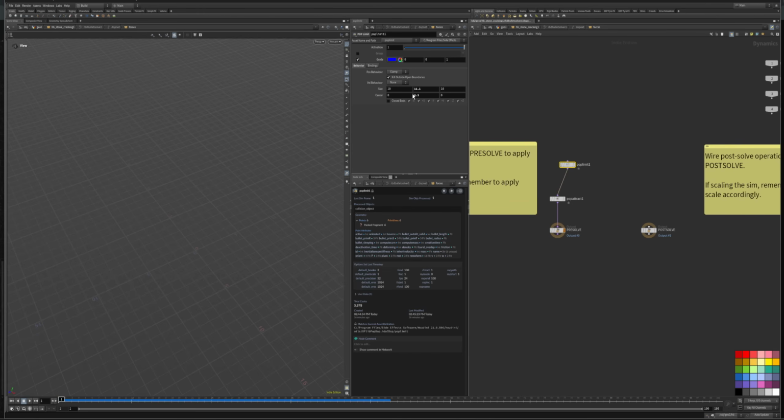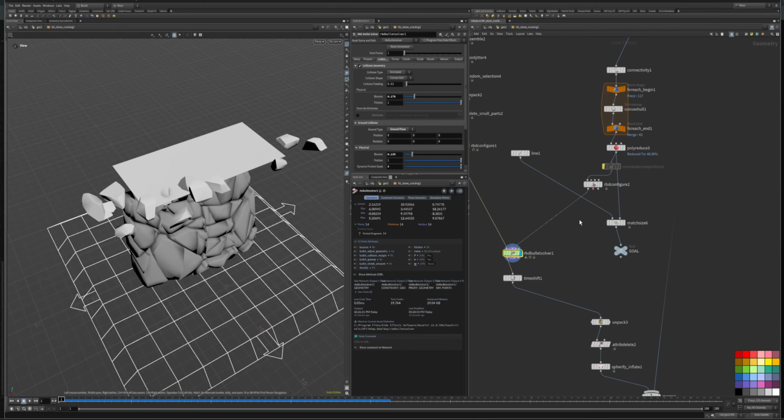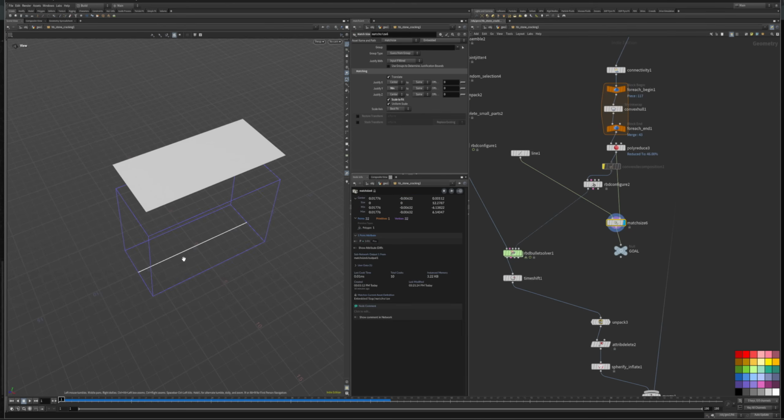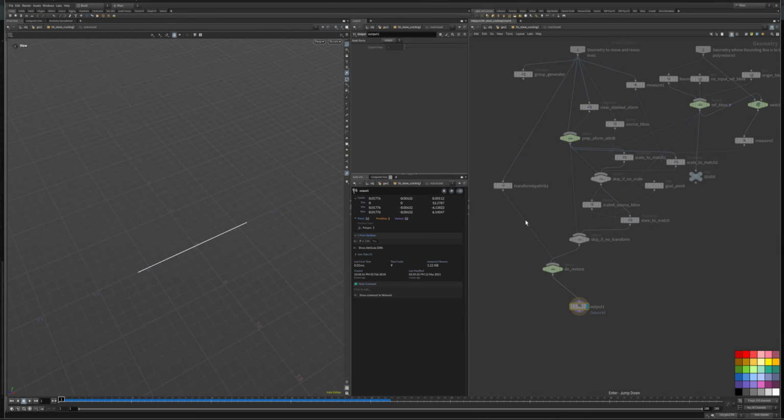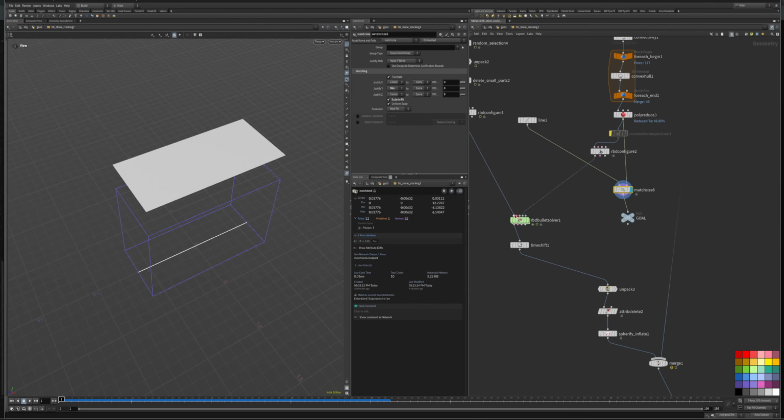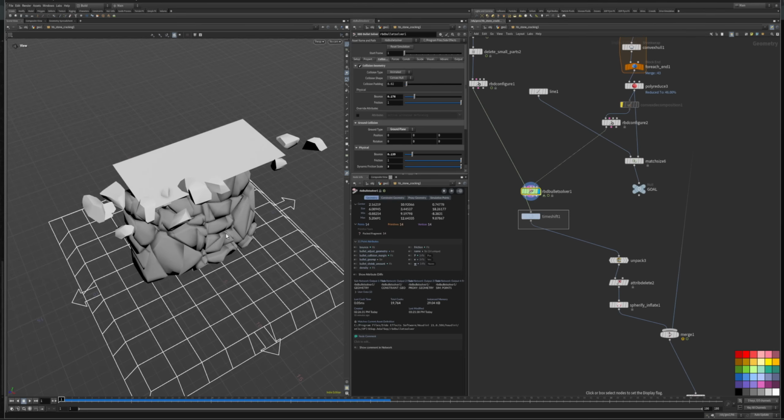And I want them to actually get attracted to a line. So I did a goal over here, which is the line that I have here. So I'm going to show the line where it is, and this is the line right here. So the points are actually going to try to go inside of the cliff itself, but not necessarily because they're going to get collision. So that's pretty much what I'm doing here. And then yeah, we have this, and then I just time shift so the simulation goes forward to the frame that I want. I put 200. So just gotta wait a little bit.